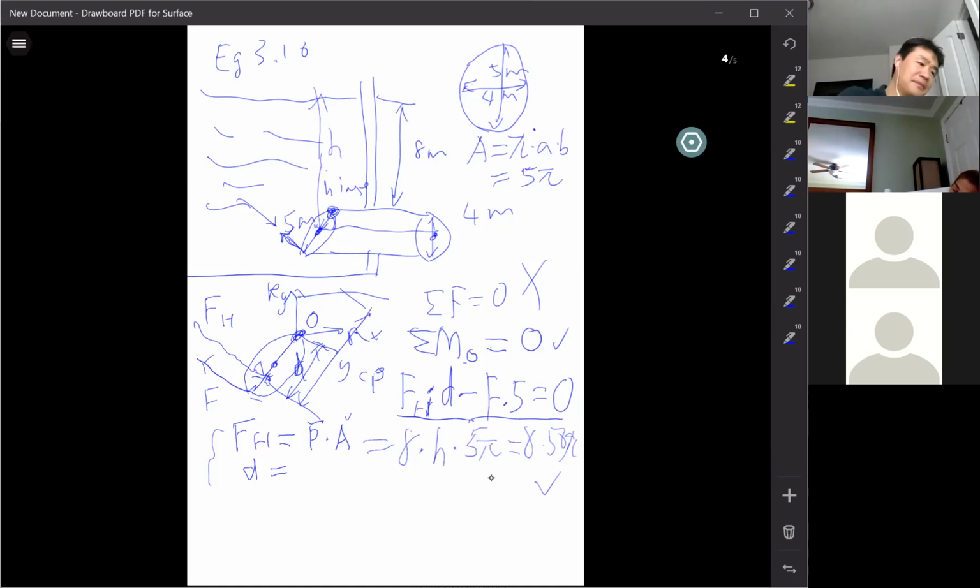For mine though, I had the sum of forces equals mass times gravity because it was static, and I used that to solve for my mass. So I need to go back and resolve for another one to verify it. I don't know how you solve for mass. You probably want to measure the weight directly. I don't have a scale small enough to measure the weight. Just find some way, maybe you put 100 of these small items together to weigh them, then divide it by 100. That's the weight of the individual. Thank you. You're welcome. Any other questions for anything?